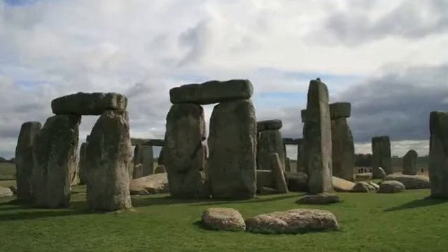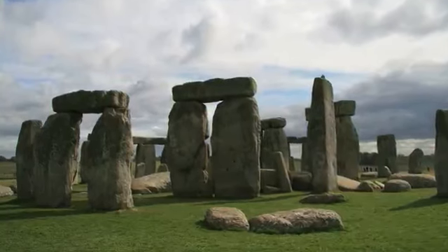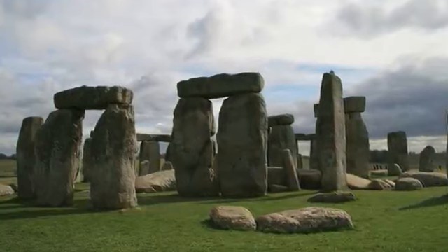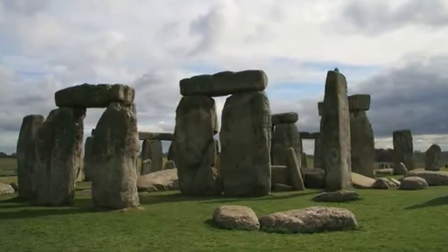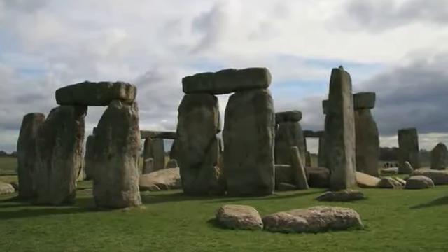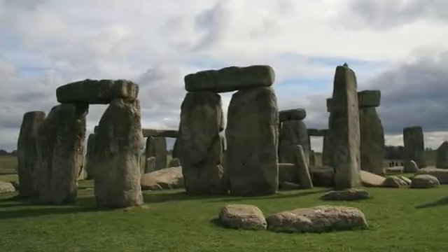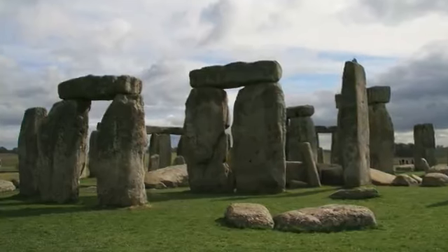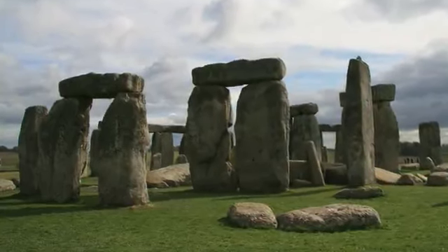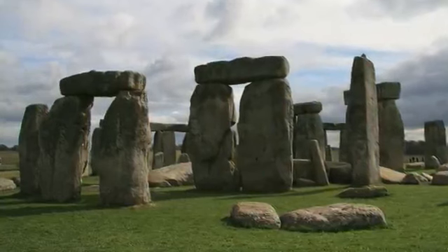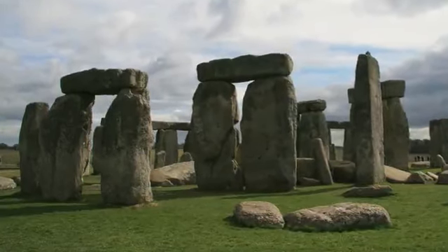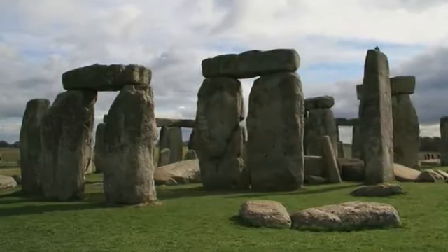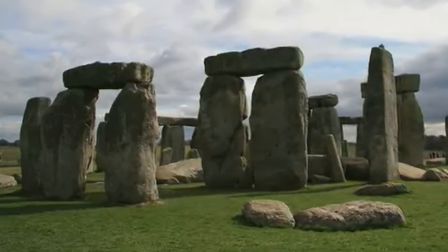One example of a pre-industrial revolution structure is Stonehenge, and I use this example to show essentially how far stone can span. In Stonehenge, the unsupported length of that beam, that horizontal member, is on the order of 10 feet. Stone is not very strong in tension, and this beam on the bottom surface is experiencing tension. We're going to learn more about beams and tension in later lectures, but for now, know that, again, stone does not carry very large tensile forces. It's not strong in tension.